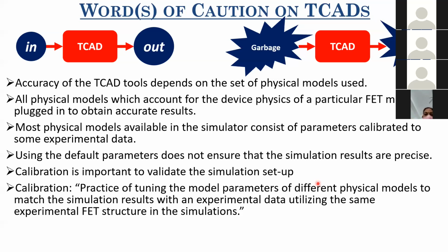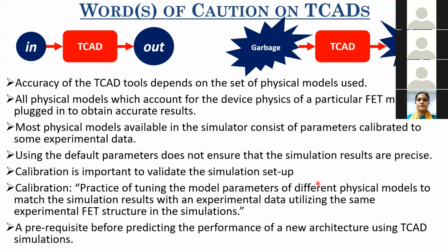And these things will come only with experience. Or I would say, once you are very thorough with your theoretical study, then you will understand these things very clearly. And this model calibration, as I told, should be a prerequisite before predicting the performance of a new architecture using any TCAD simulation. So calibration is something that you need to do always before going for any TCAD simulation based study.